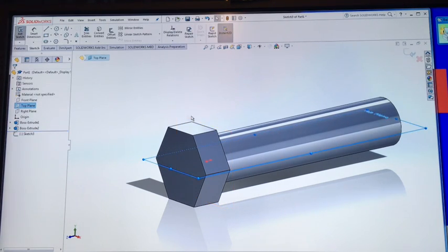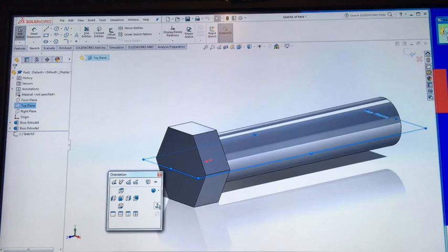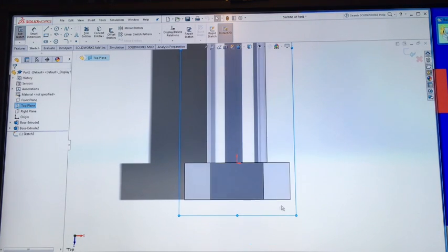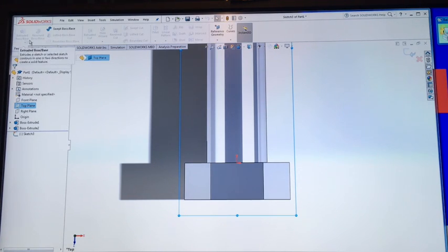Now, we've done revolves previously, 360-degree revolves with the washer and the pivot pin and the pulley wheel. The tools that we use for creating by adding, be it the extruded boss, revolve boss, or the sweep or loft, you can also use those same tools to cut.